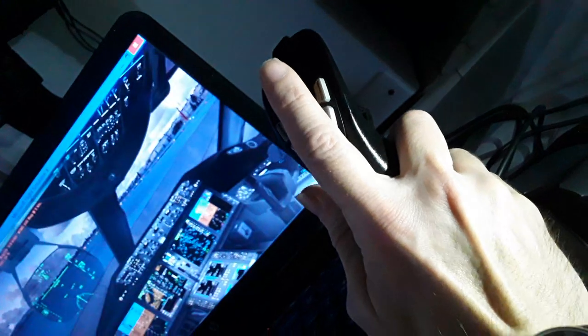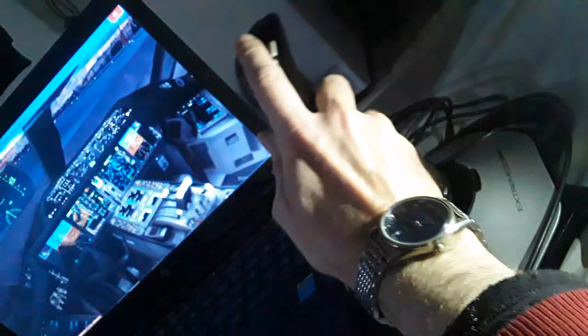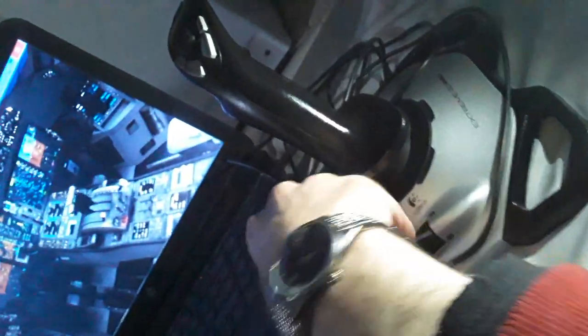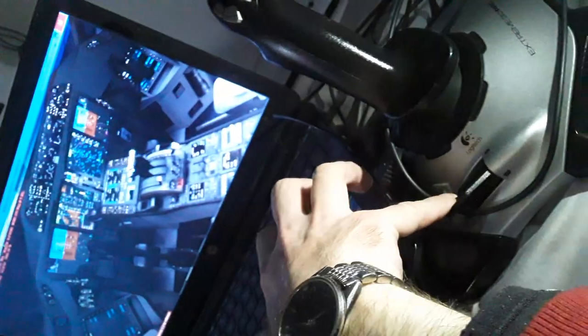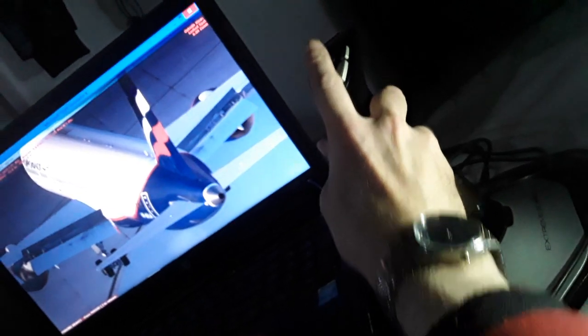All side stick deflection, full left, full forward, full right, full left, and the rudder pedals also. The thrust levers, as I told you over here. You can use together with the flight controls. Also a little bit the outside view, so you will see again how you climb over here using the horizontal tail for climb and for descent.